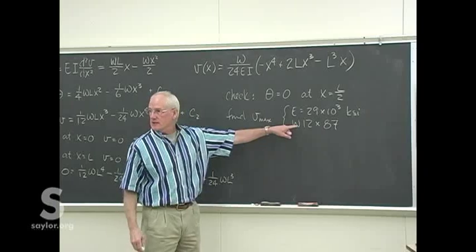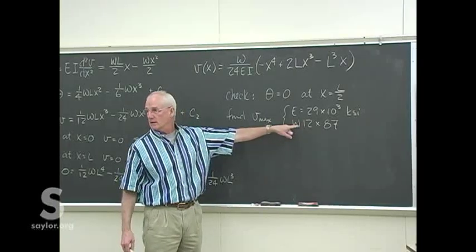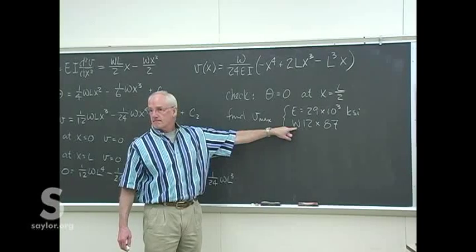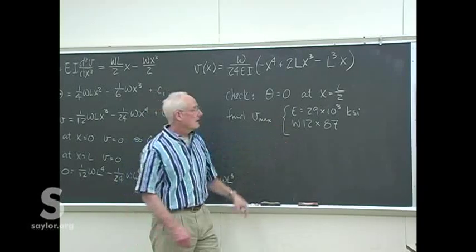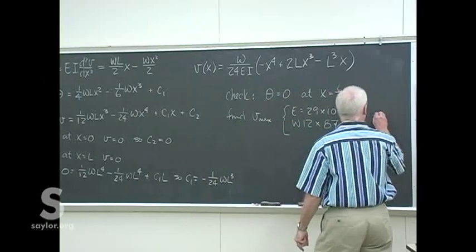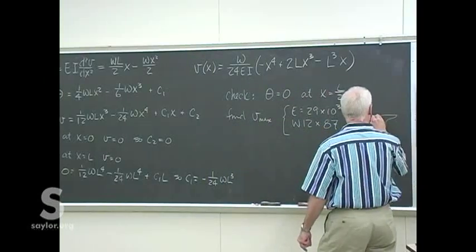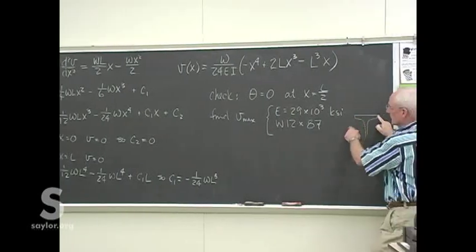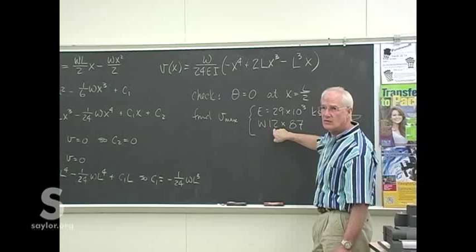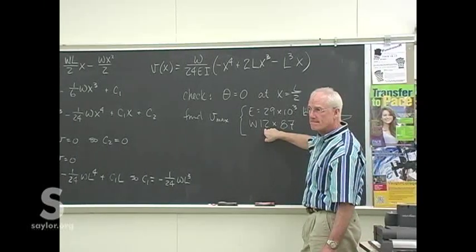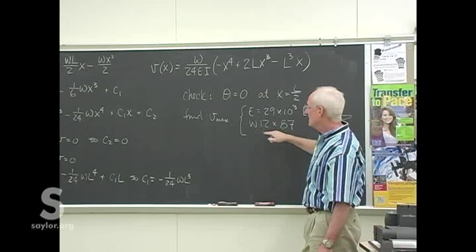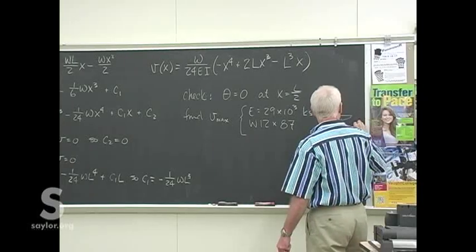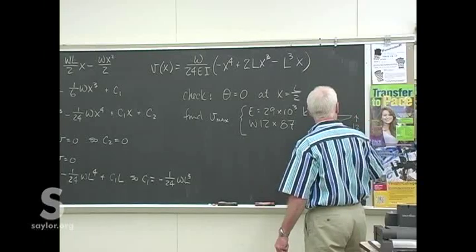Remember what these two numbers mean? What's the 12 mean? Well, actually, first, what's the W mean? Remember offhand? W means it's a wide flange beam. So it's an I-beam with what's considered a wide flange on it. So that's the W. What's the 12? 12 was the approximate height of the beam in inches.